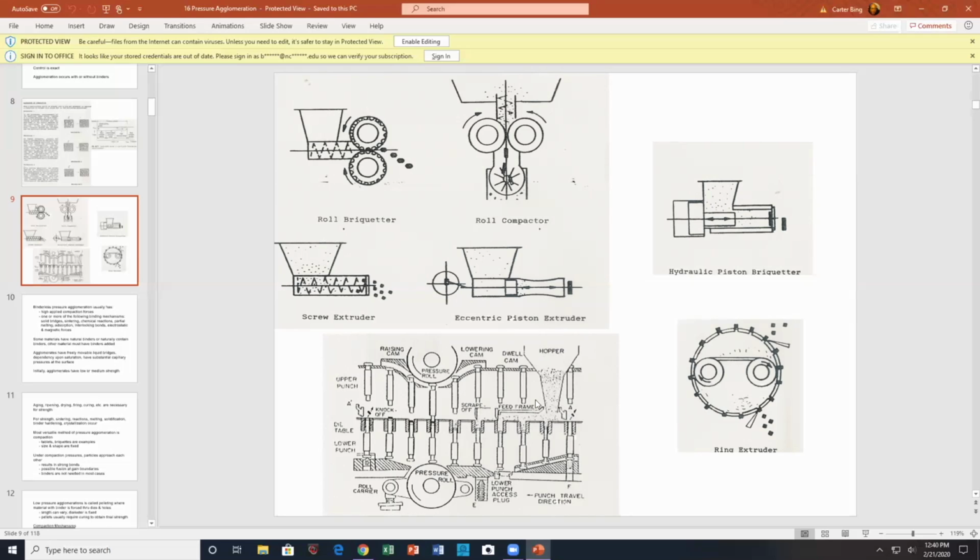Hopefully, gravity feed without electrostatics is going to occur in here. And so you have some sort of free flow in here as this thing comes sweeping by. By the way, this is rotating. Punch direction of travel. This thing's rotating, and it fills the die, where the pill has been popped out. The lower press has been withdrawn, leaving a place in there. Hopefully you pulled in mostly solids and little gas. And then you scrape off the top portion.